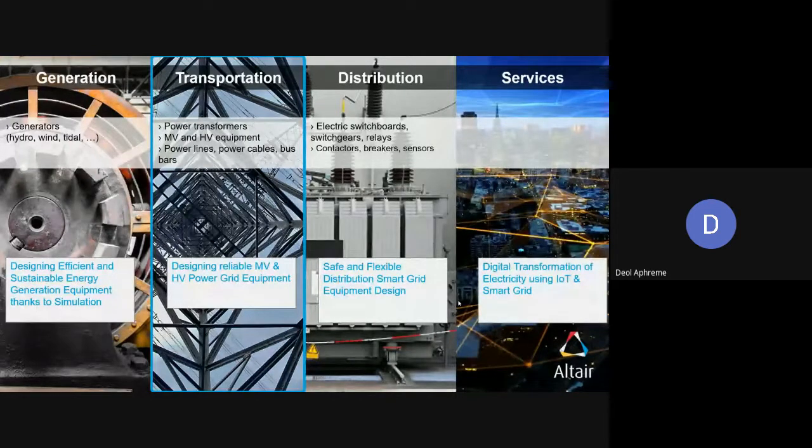Distribution is very important, simply because of isolated incidents and particular requirements. Say industry X, industry Y, and industry Z are on the same grid, and industry X went through some fault and the entire thing shut off. It shouldn't have a global impact on the entire grid, but instead only industry X should have some sort of individual safety requirements. So that increases the requirement for all these safety devices, isolators, relays, and all of that.